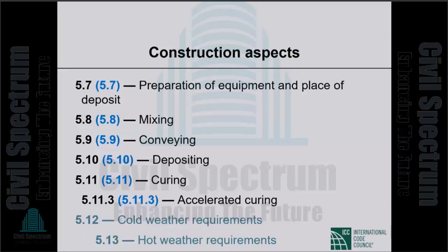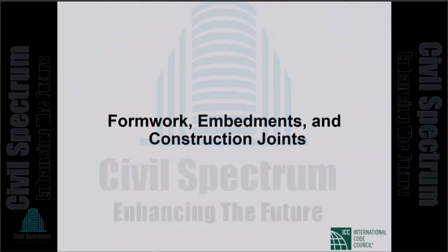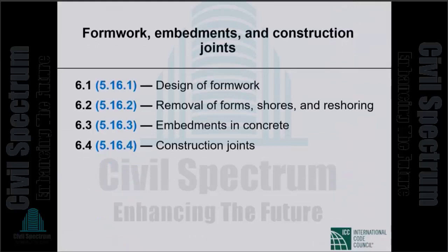So these are all major topics that I do not have time to discuss, but please make sure that you understand them to be important and to follow not only the requirements in the code, but also sound practice. Formwork, embedments and construction joints, there are requirements given. This again should be taken seriously. Design of formwork, removal of forms, shores, reshoring.